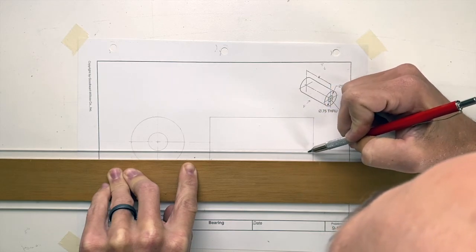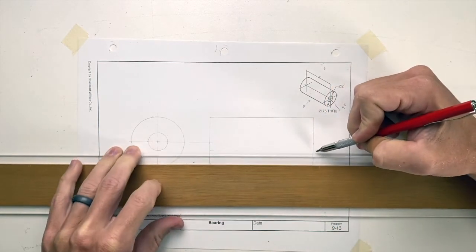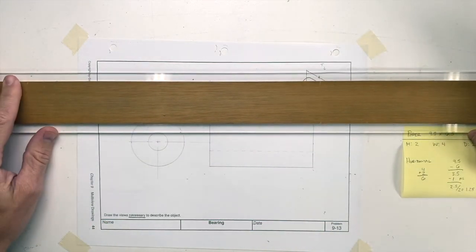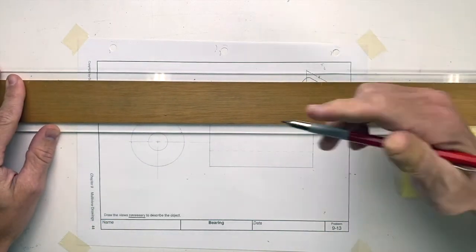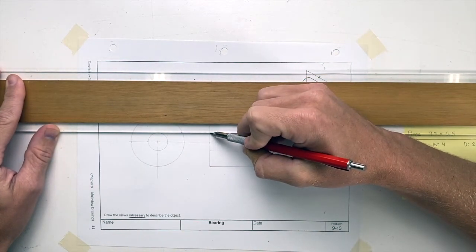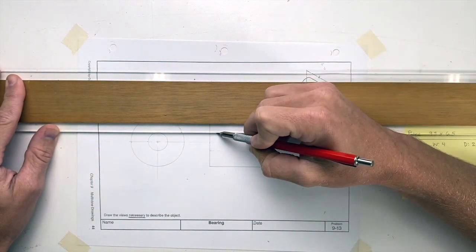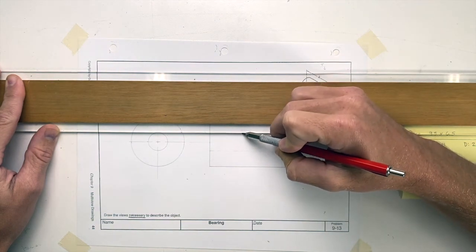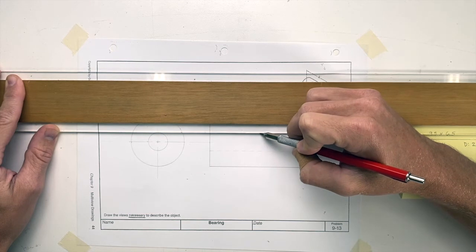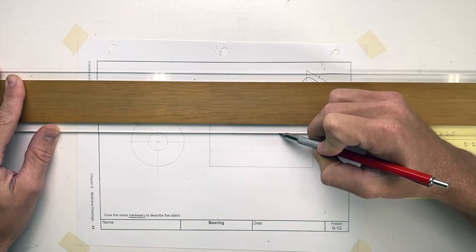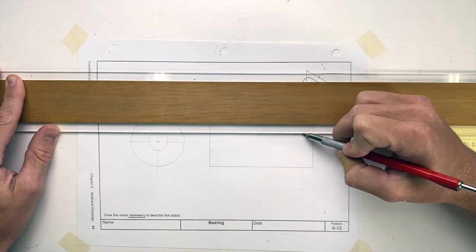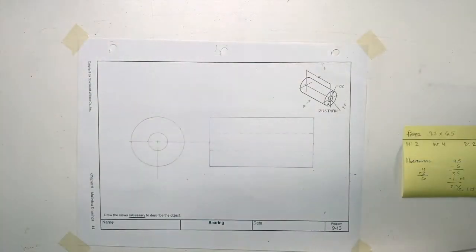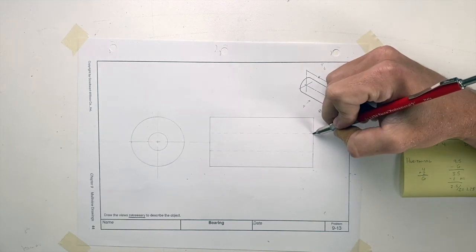Your hidden line should also end into the object line, so you shouldn't start your space right when you get started, but you should actually connect it with that object line first, like so, and then start your spacing. If you have to stretch your last dash, then do so. Or just give a small dash to make it work. So right here there's a small space in mine, I want that to continue.